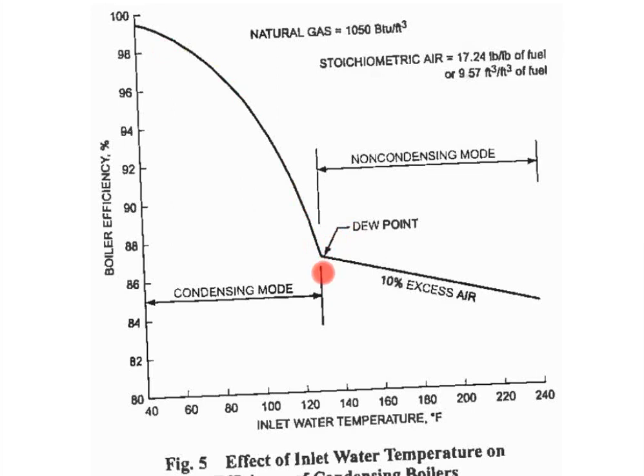So the reason I'm showing this to you is most of you have probably seen this chart before, or a similar one. The more hours we can operate with cold return water, the more efficient our boiler plant becomes. If I design all your plants for 180 supply, 20 degree delta T, I'm going to pretty much get the rated efficiency of the boiler. But if I can get that boiler to operate at colder temperatures, either for all of the year, such as radiant, or part of the year, outside air reset, I'm going to be much more efficient.